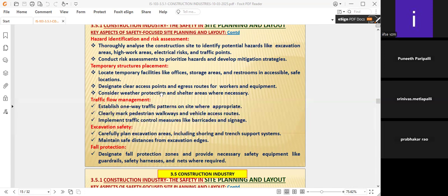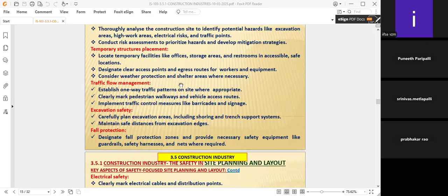Normally, at the excavation stage where there will be more water, the area should be covered like a cricket pitch. We have to cover it with tarpaulins and see that water is not stagnated, giving a slope to the tarpaulin so that water flows and there is no stagnation in the excavation or where wells are taken. Like this, weather protection and forecasting must be done, and shelter arranged not only for the workplace but also for the workforce.